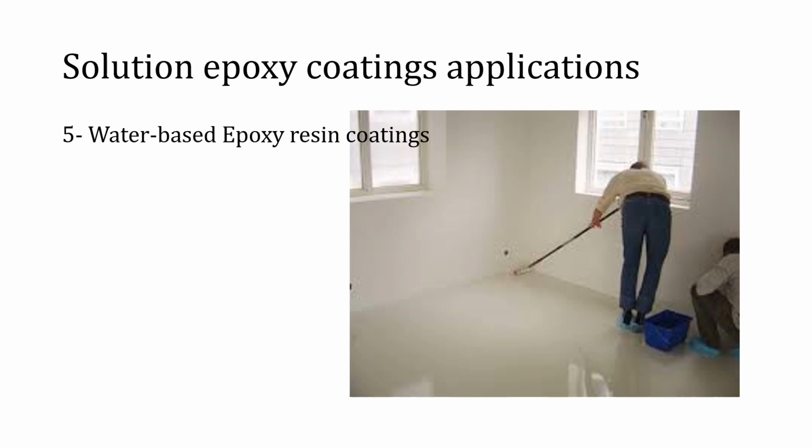Compared to solvent solution epoxy systems, in the epoxy emulsion systems more heat is required as the film formation involves the evaporation of water. The flexibility of the emulsion epoxy coating can be improved by the addition of alkyd, polyester, or acrylic resins, and for the curing, polyamines and polyamides may be employed.